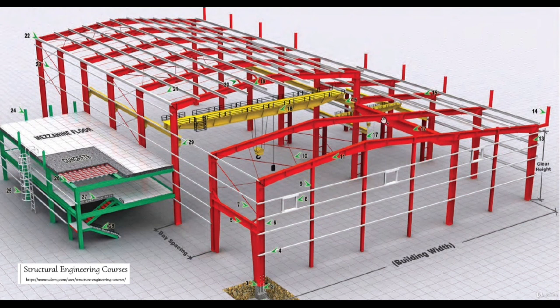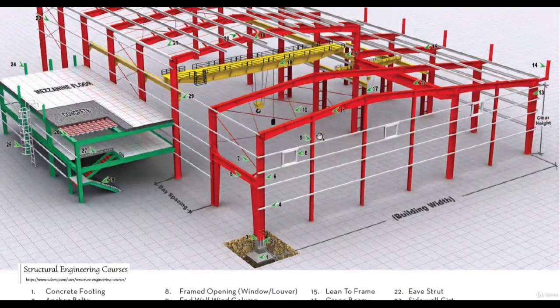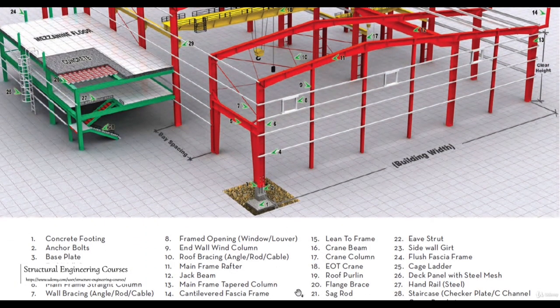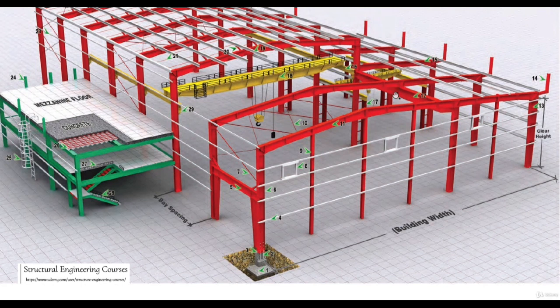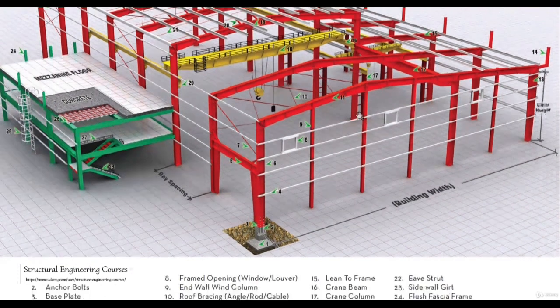So this span must be very long, and the bending moment must be considerable for this type of arrangement. So to break this span from this point to this point, or to provide support to this portal, we provide this jack beam. The purpose of the jack beam is basically to break the span of a portal. How? By modeling a beam perpendicular to the direction of the portal, from this point to this point. There's one more thing I want to explain in this jack beam concept. Sometimes the client does not want a column here. They might want a free space here. So in that case also, we make this jack beam arrangement here.